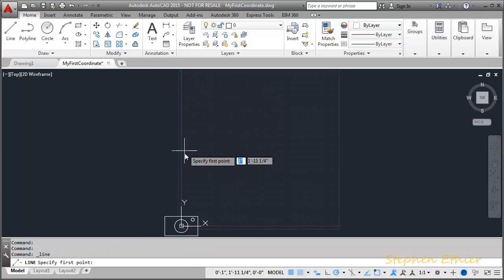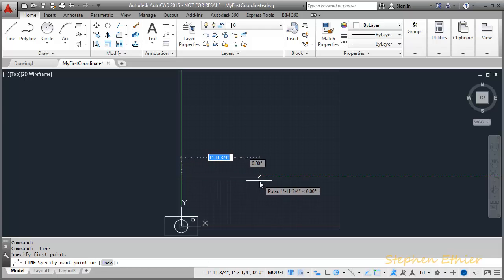Let's go up to the Line tool and pick the line anywhere to start. We'll pick against the side here at 0 in the X direction. Drag our cursor over. To enter the line 2 foot 6 inches long, we type 2'6". The idea is using the apostrophe to separate the 2 foot unit and the 6 inch unit. We don't have to put quotation sign to represent the inches. If we don't put the quotation sign, it automatically uses the integer as inches.